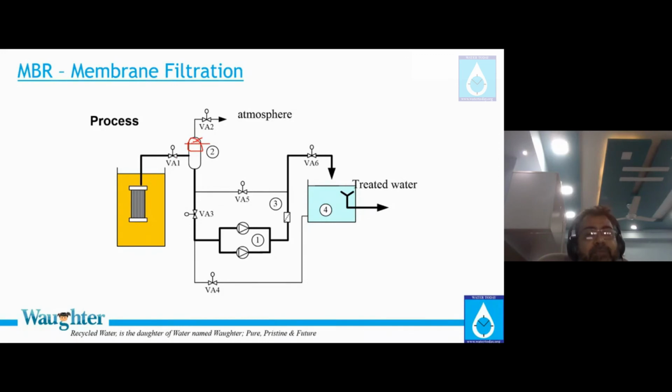And if this particular equipment's job is to suck on a continuous basis, because of this more air deposition, this air layer will start going low. We do not want this level to start going below a certain level. Otherwise, there is no purpose of giving this tank, as air is anyway sucked into the line. The entire purpose of this membrane degasification tank was to make sure that the bubbles go here. So you can put a level switch or a level sensor here as a safety.